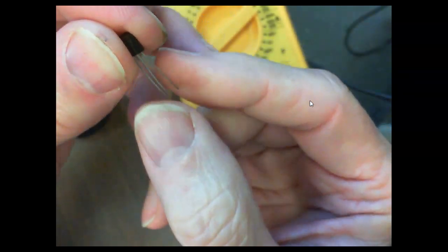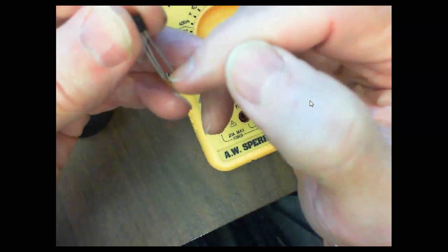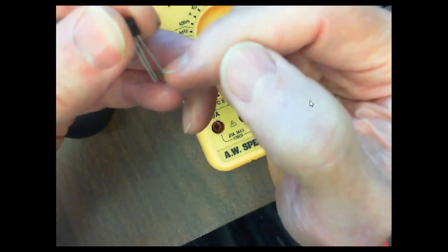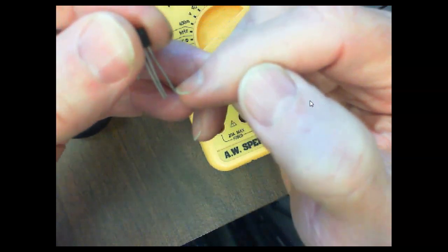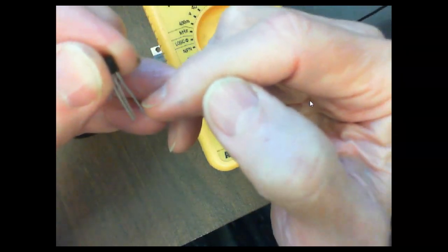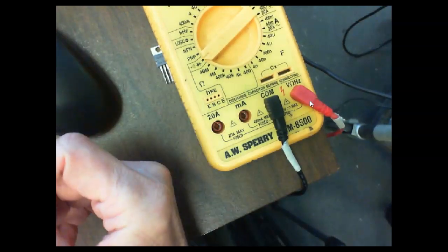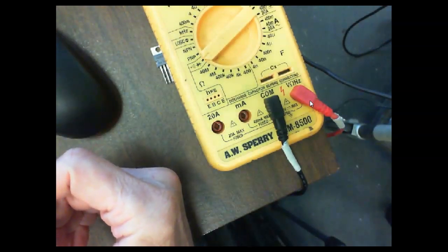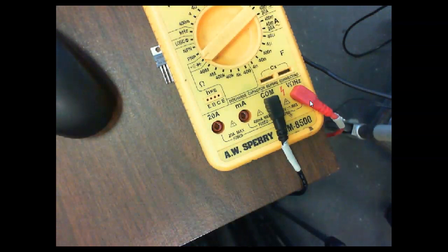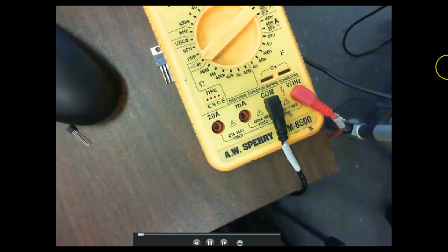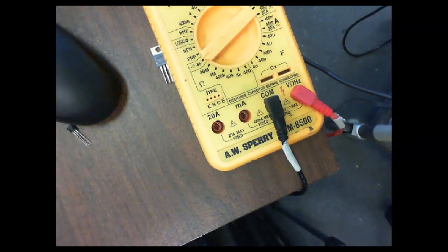You understand that? But you're going to have a resistor connected to it. So I'll have a resistor connected to the collector lead, so I don't have to get on the collector lead. I can get on the resistor that's connected to the lead. And you'll learn that real fast with transistors, that you very seldom can get to the lead without accidentally, not bending them, but slipping. You're over here looking at your meter, you slip off the lead, you touch two leads together, and you blow your transistor just like that.